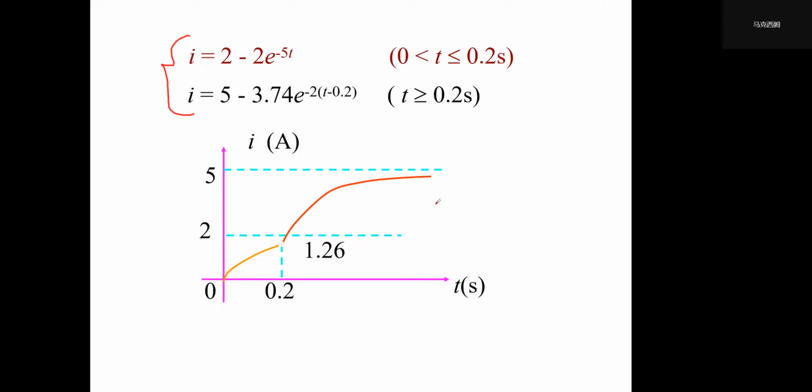It's a sectional function. And we see those two parts contain different time constants. So we actually change the structure of the circuit, and we change the corresponding time constant. So with this example, now we can see the step response of this first order circuit.